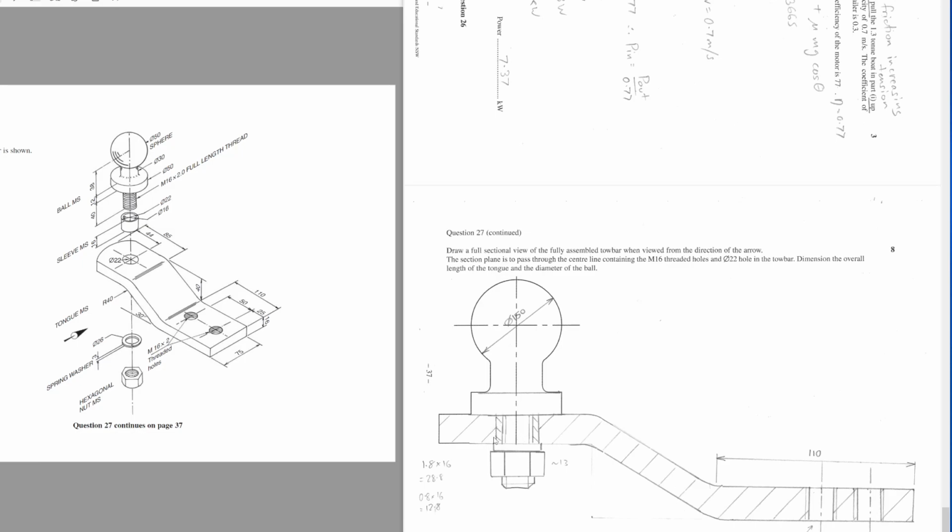Anyway, then I've got the sleeve. The sleeve needs to be hatched differently. And then we've got dimensions. So I've got 2 dimensions, 2 dimensions, 2 different kinds of hatching, that thing there as well, maybe. So 1, 2, 3, 4, 5, it's 8 marks. I mean, there's going to be other things we're looking for. The general shape is definitely 1.